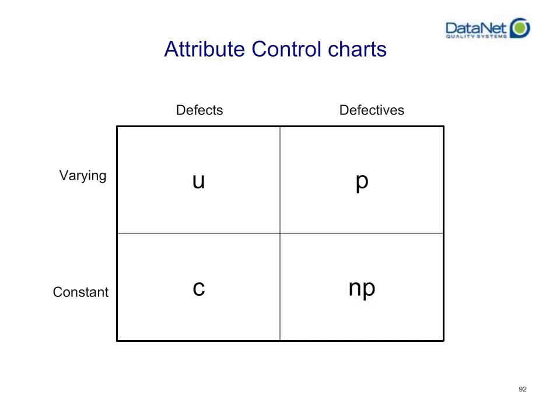If you are counting defectives and you have a varying lot size, you must use either a P chart or a Q chart. If, however, you are using constant values, you can make some assumptions to make calculations easier: for defects with a constant lot size, you can use a C chart, and for defectives with a constant lot size, you can use an NP chart.